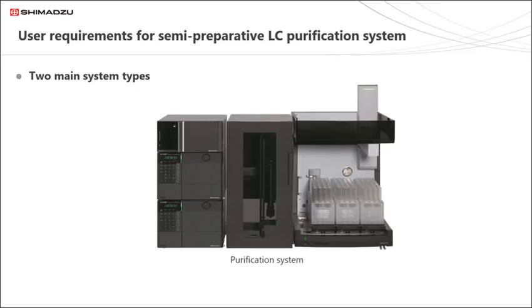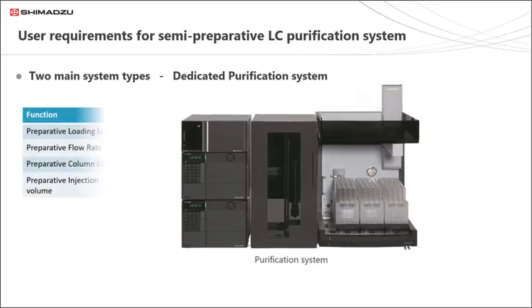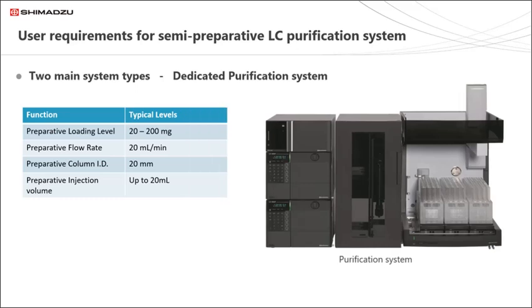There are 2 approaches to system design. If sample purification workload is high and there is no limit on space, then a dedicated system makes sense. Analytical scout runs would be completed on a separate analytical system.